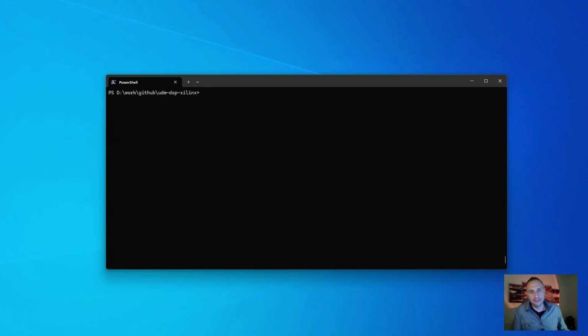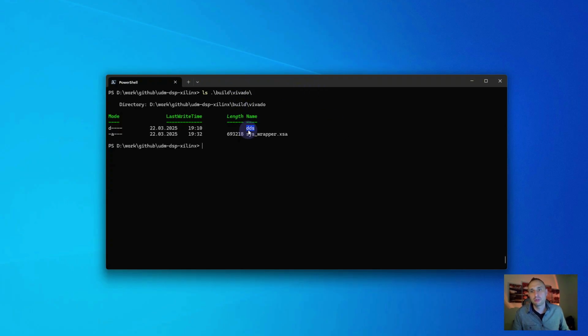Let's consider how to handle the DDS Compiler IP core with Vitis 2024.2 on the development board. For a Vitis project, an XSA file is required. So in order to get an XSA file, we need to synthesize and implement the Vivado project. The script for automating the Vivado workflow, run Vivado, is used with the DDS target. This script will create the Vivado project and export the XSA file. I already did this since it's a time-consuming process, and here in the Vivado subfolder the DDS folder can be found with the Vivado project itself and the exported XSA file.